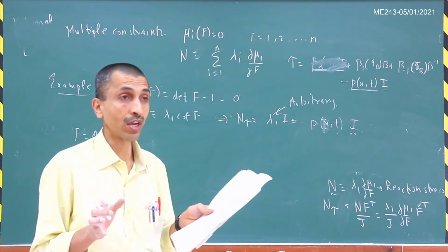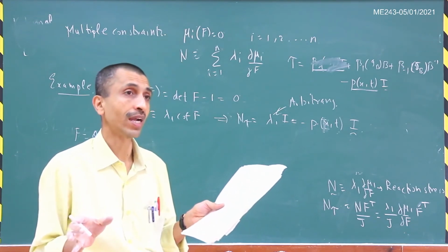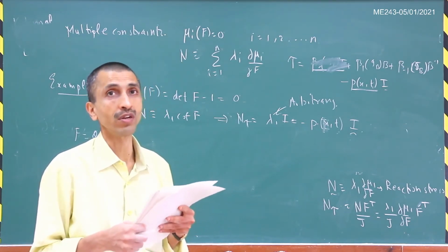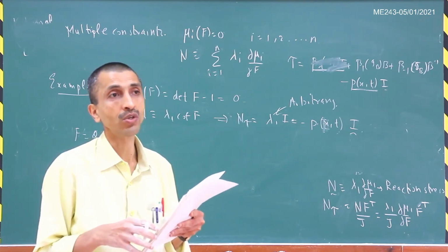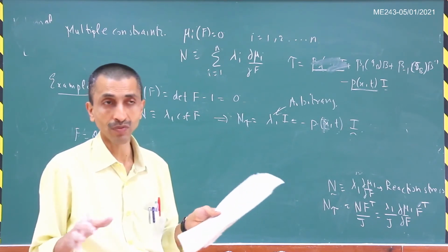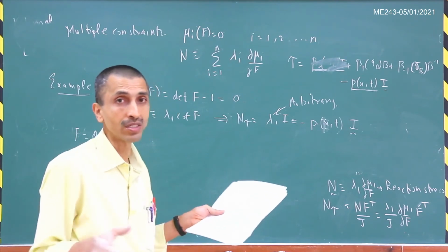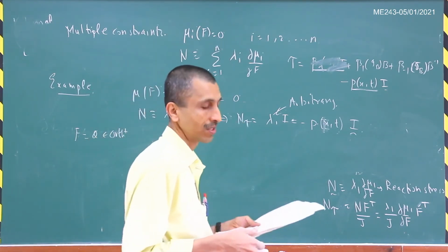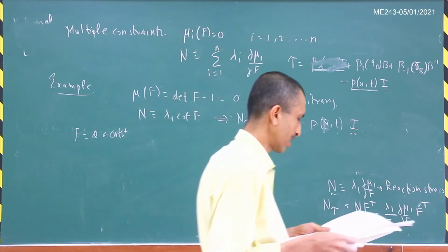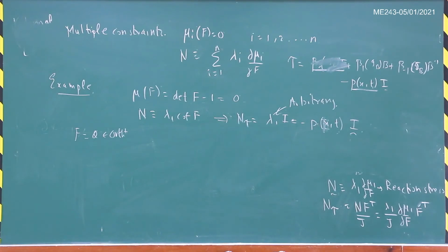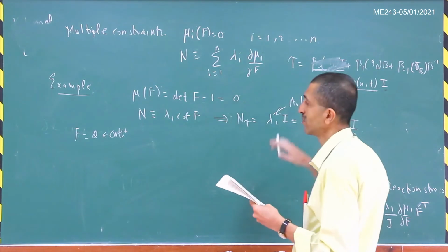Of course, we are not saying that there is no stress. We are not saying that the stress is zero. All we are saying is that in a rigid body, it is constitutively indeterminate. That means you have to determine the stress by using the balance of linear momentum and the boundary conditions. So in a completely rigid body, the entire stress tensor would be constitutively indeterminate. So this is something about how to handle internal constraints within a system.